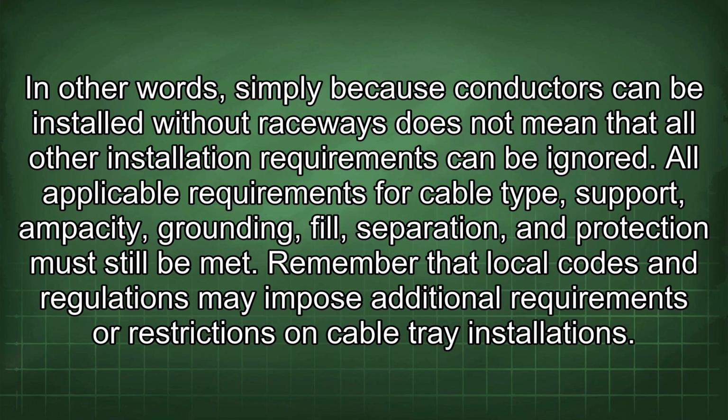In other words, simply because conductors can be installed without raceways does not mean that all other installation requirements can be ignored. All applicable requirements for cable type, support, ampacity, grounding, fill, separation, and protection must still be met.